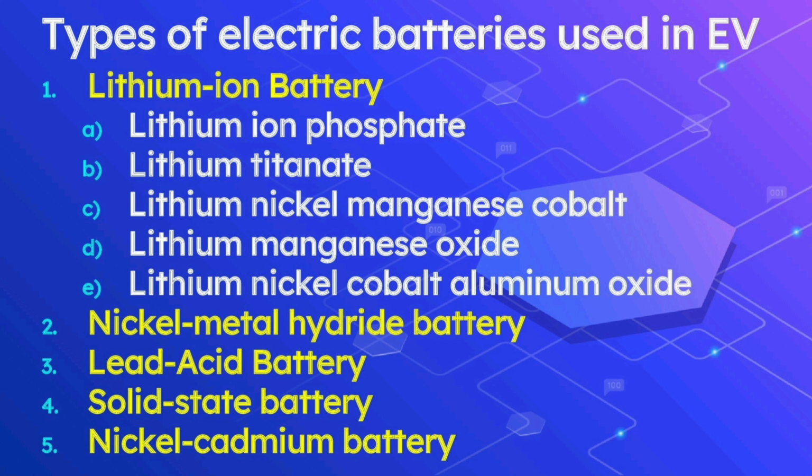And what is safety? This point relates to factors such as the thermal stability of the materials used in the batteries. The material should have the ability to sustain high temperatures before becoming unstable. Instability can lead to thermal runaway, in which flaming gases are vented. Fully charging the battery and keeping it beyond the designated age reduces the safety.